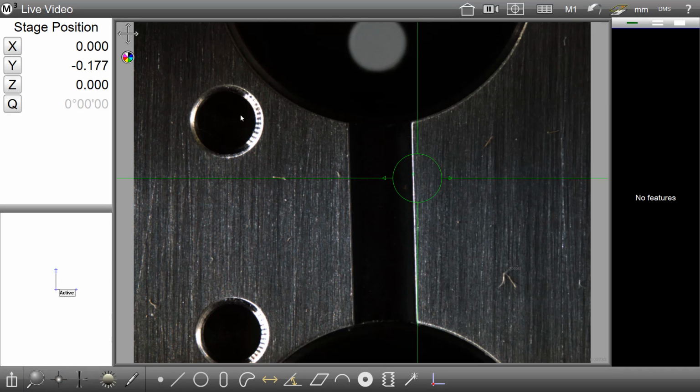In the M3 V3 software, we have made a change to the behavior of the Simple Active Crosshair. As you will see, the new Simple Active Crosshair can be sized, and its edge detection sense can be set using the sizing and edge scan handles as seen here.